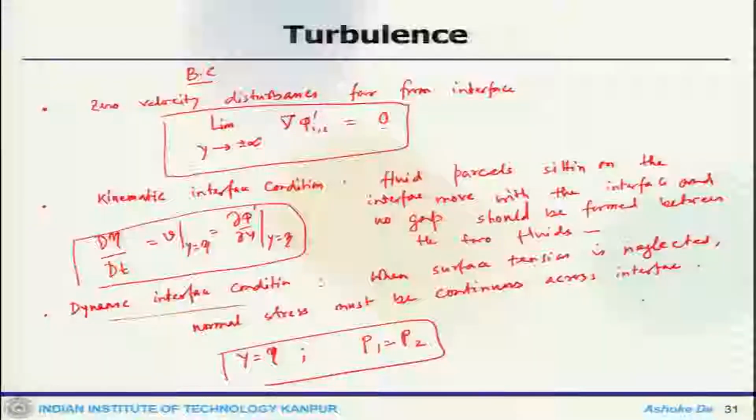Welcome back. Let us continue the discussion on this linear stability analysis. What we have done, we have already looked at different types of analysis, and we are going to look at two different kinds of normal mode analysis here. One is the K-H instability, another is the one with viscosity, where we will come across the Orr-Sommerfeld equation. So, for K-H instability, we have taken a situation and derived the linearized perturbation equation.